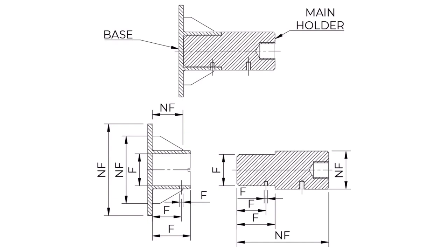Functional and non-functional dimensions. When we are dimensioning an object, naturally, some dimensions will be more important than others. Some dimensions will be critical to the correct functioning of the component, and these are called functional dimensions. Other dimensions will not be critical to correct functioning, and these are called non-functional dimensions. Functional dimensions are obviously the more important of the two and, therefore, will be more critical when making decisions about the dimension value.